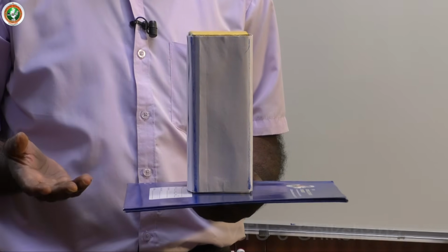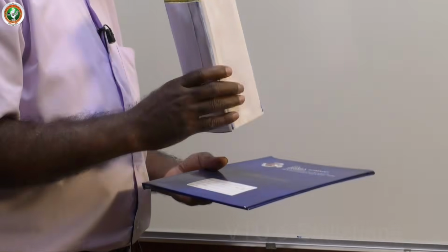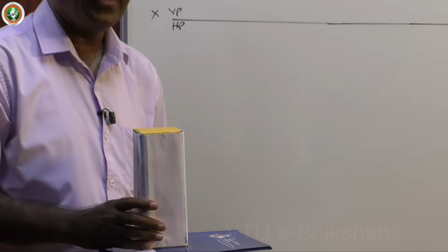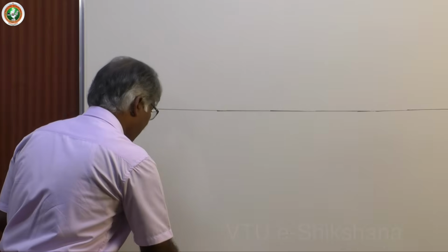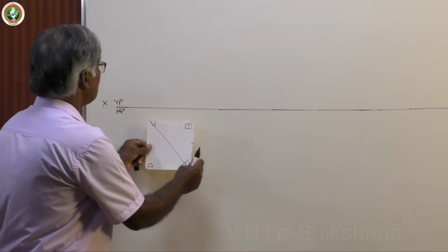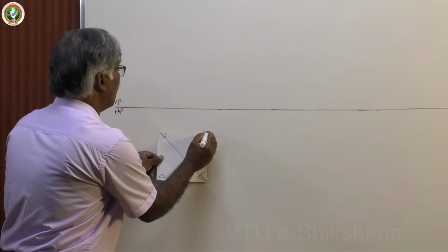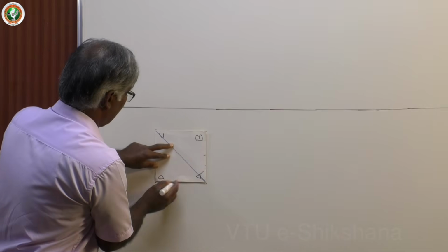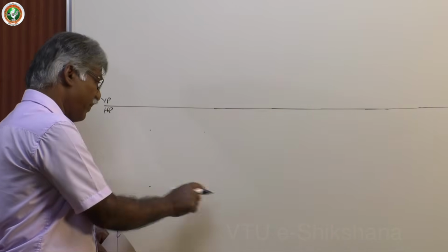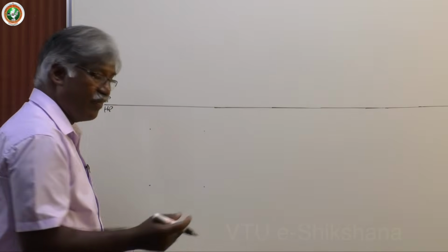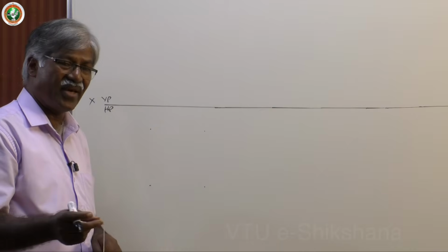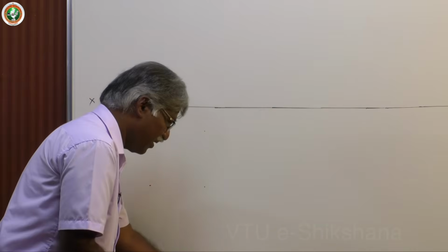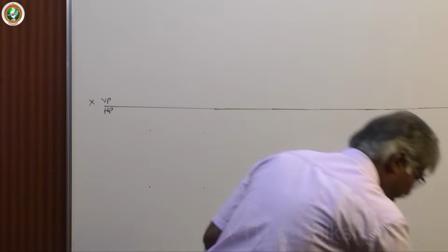So you start from the top view. Let me draw the first position of the problem. Now the top view is a square with one base edge perpendicular to VP. So you know how to draw the square. Geometrically, you draw a vertical line, draw perpendiculars and do it. Or in computer you can easily use rectangle by 2 points, shift to the same size on both sides and you get the square. Now let me keep the top view properly.